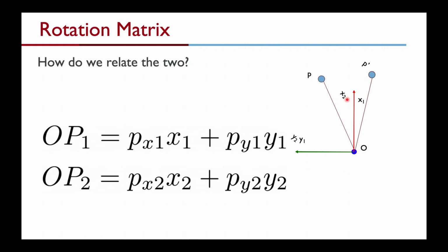So we are rotating. When we multiply the unit vectors x1 and x2 with the rotation matrix R, essentially geometrically what is happening is we are rotating the entire coordinate frame to align with the original frame 1. And what that means is point P is also getting rotated to a different position P prime in my original frame.